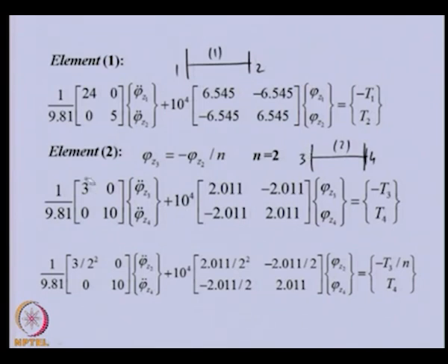So, you can see this particular mass moment of inertia at gear node 3 needs to be divided by the square of the gear ratio. This we need not divide, because this particular angular displacement is the same as that of node 4. This is not related with the gear ratio, so we are keeping this as it is.